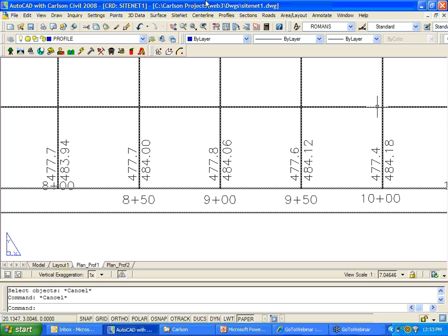In the sewer network labels in plan view, you lay out the sewer network, which I wasn't really showing you much of plan view. But if I go and grab that label and scoot it over where it looks good, and then there's a change to the design, in plan view it will stay. But the labels in the profile are going to be recreated. So that's a good one. We'll put that on the list for next round as well. Okay.